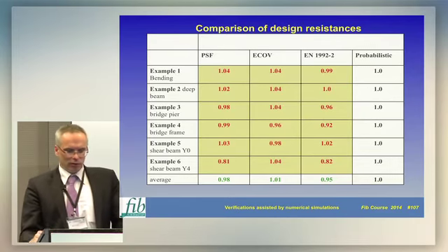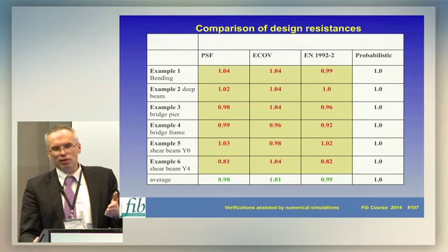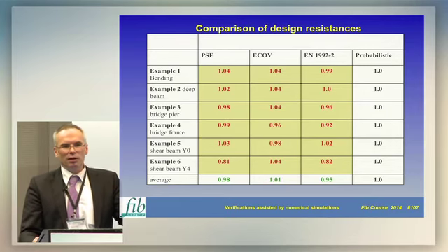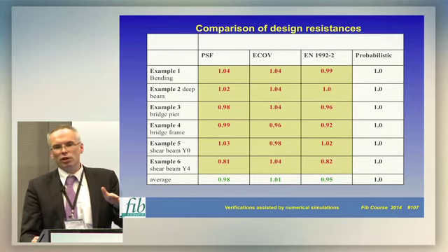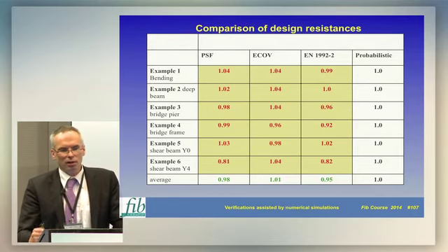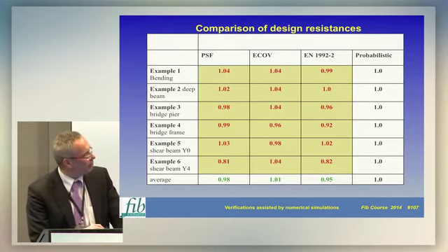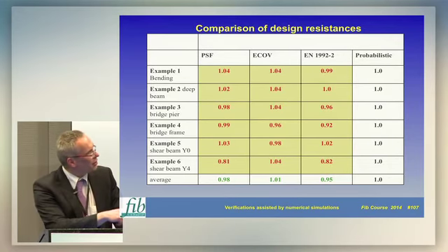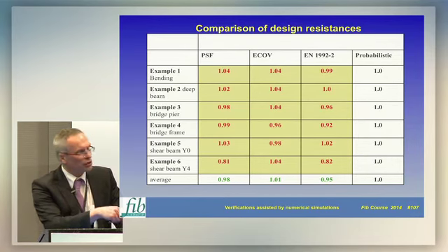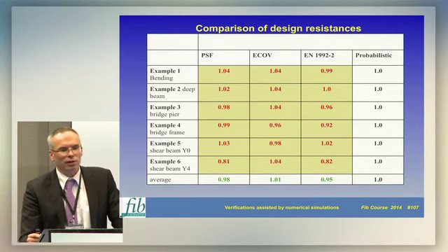But the disadvantage of this PSF approach is, for instance, that maybe it would be then difficult to use the same analysis to check the serviceability limit state, because you are using so low properties that the serviceability limit state check may be too conservative. So the other method that is favorite of mine is this one from Eurocode, where you can almost then have single analysis, and use it to check both ultimate as well as the serviceability limit state.